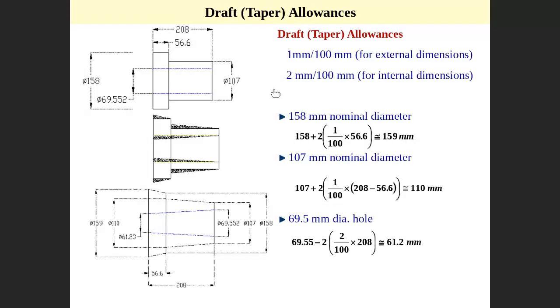And finally is the taper allowance. For taper allowance, you need to make it taper here. Why do we do taper? To facilitate. The only reason to add draft allowance is to make it easy. This dimension is being added only to easily take the part out of the sand, as we described. Then we make the taper. Then every surface here will be made taper.